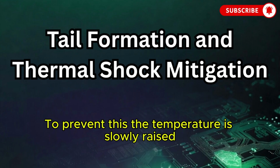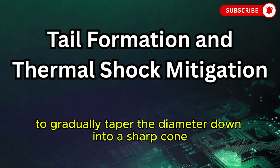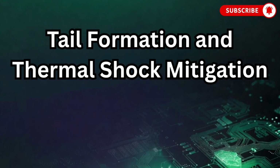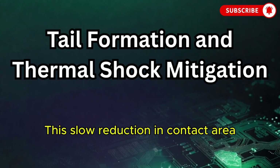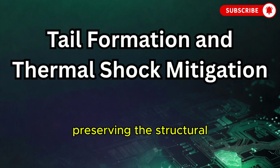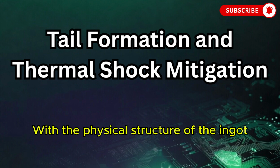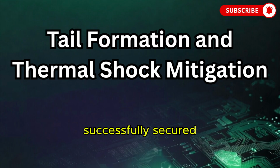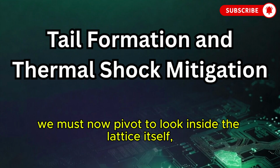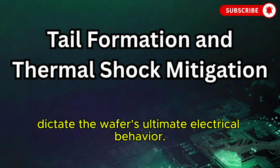To prevent this, the temperature is slowly raised while the pull rate is adjusted to gradually taper the diameter down into a sharp cone, or tail. This slow reduction in contact area gracefully decouples the ingot from the liquid melt, preserving the structural perfection of the usable silicon body above it. With the physical structure of the ingot successfully secured, we must now pivot to look inside the lattice itself, where subtle chemical interactions during growth dictate the wafer's ultimate electrical behavior.